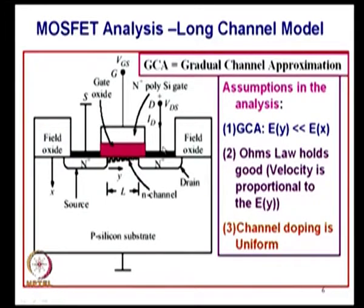The most important simplification which is done in the Shockley analysis is GCA, that is gradual channel approximation. What is the meaning of that? The GCA, gradual channel approximation, assumes that the electric field along the channel, I marked it as y direction, is much smaller compared to the electric field along the vertical direction, that is x is marked as vertical in my case, which would mean that you can ignore the 2-dimensional effects while you solve for the carrier concentration in this direction.